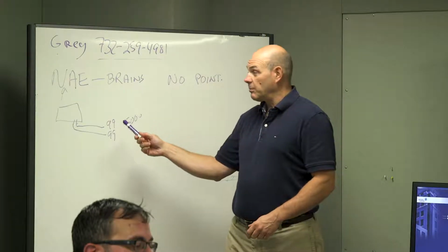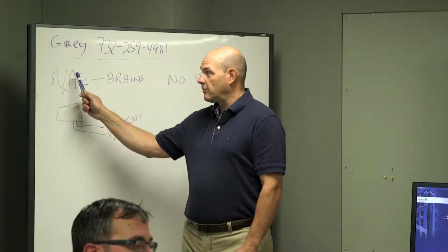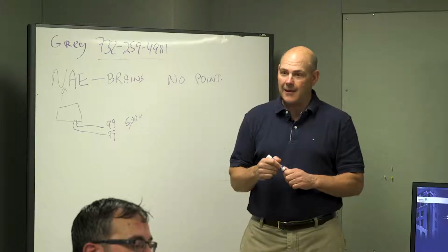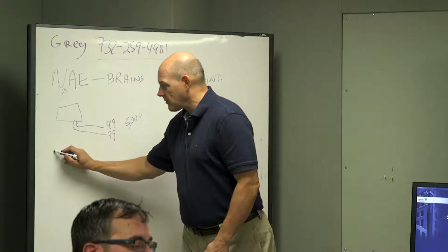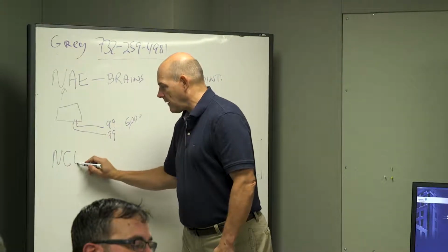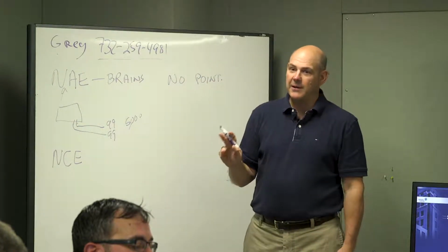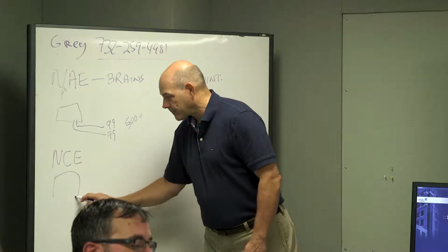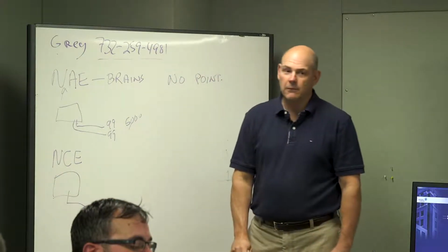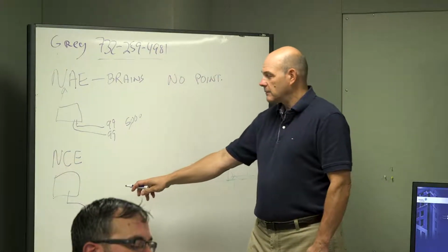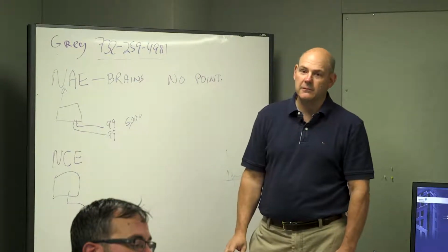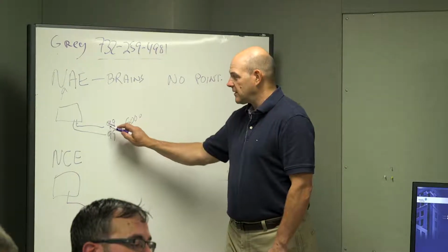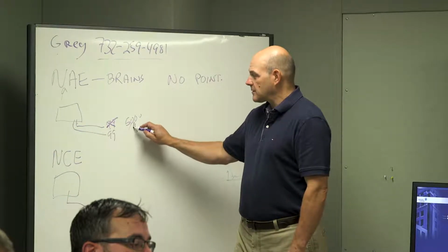So inside the chiller panels and the cooling tower panels, you have an NAE. The other panel we have is called the NCE. The difference between the NCE and the NAE is that the NCE only has one communication loop going out to drive, so it cuts this out, but it still has this point count.